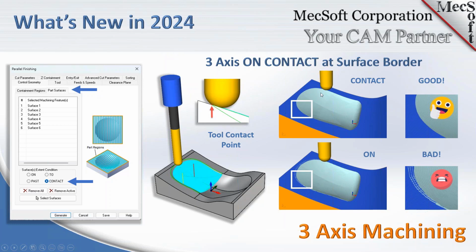So on top, we see the 2024 contact condition, nice, clean cut around the parting line. Previously, in order to get that, we actually added masking surfaces or guide surfaces to help guide the tool past the parting line. Now you don't have to do that for a specific set of cavities. So I'm going to show this as well.